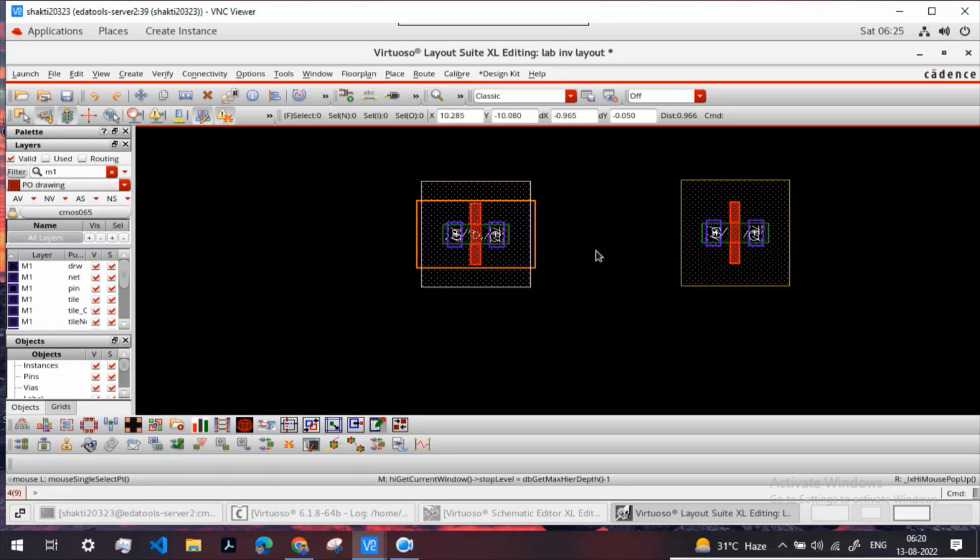For making the PMOS inside the p-type substrate, we first need to create an n-well, which is a region of n-type substrate, and then there we dope p plus source and drain to create a PMOS. For NMOS, I don't need any p-well as such, because the whole black region is itself p-type substrate.